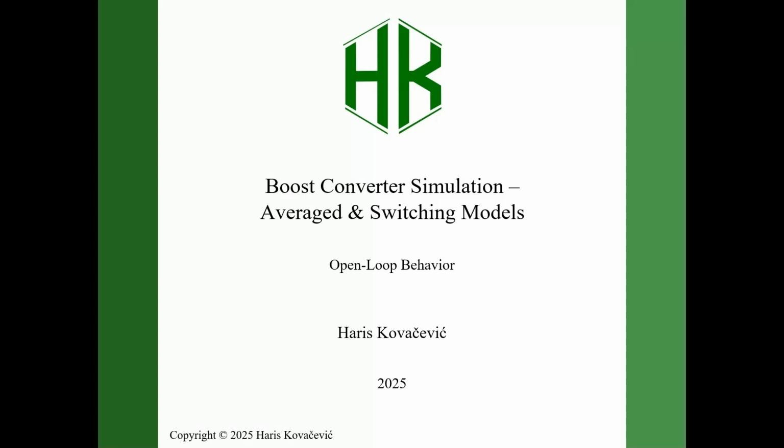In today's video, we will explore the open loop behavior of the boost converter using two LTspice models. An averaged continuous conduction mode model for fast analysis of duty to output behavior, transient response, and small signal dynamics. A full switching model with PWM modulation, MOSFET driver, diode conduction, and realistic ripple.